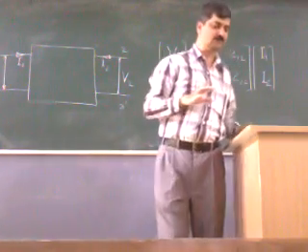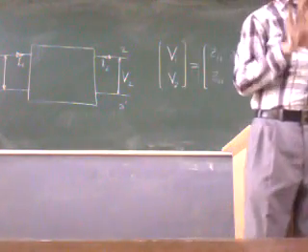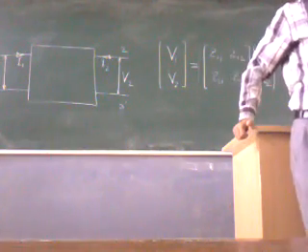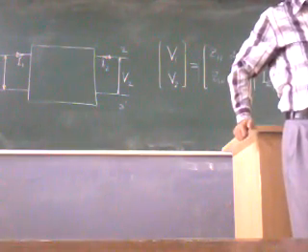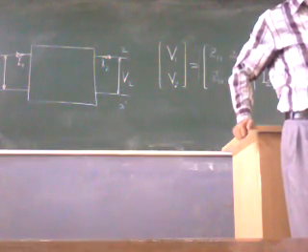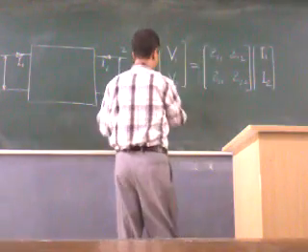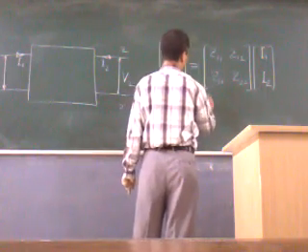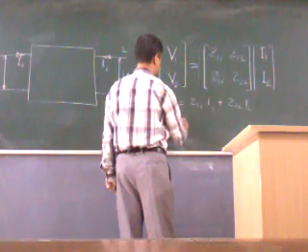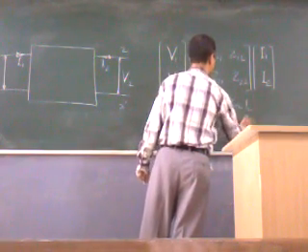In 2-port network, we are not learning any new thing. First, we can go for Z parameters. For a DC circuit, it will be R parameters directly. Z parameters provide us a way to get 4 impedance values which describe the system functioning fully. So the equations are V1 is equal to Z11 I1 plus Z12 I2. V2 is equal to Z21 I1 plus Z22 I2.